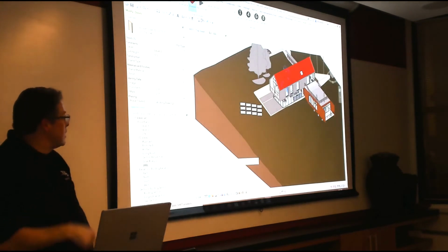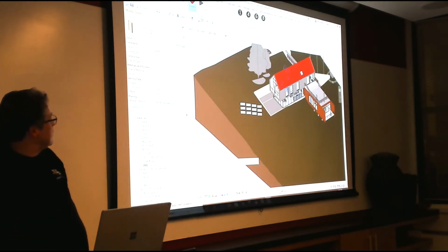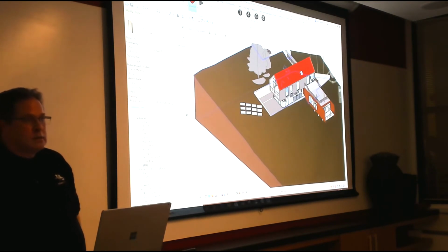You notice that Grasshopper ran, or maybe you didn't, but here you can see that the marks and the comments are now copied. So we read the mark parameter and put it on comments for all the doors in the project. All 10 in this case. But we can have some fun with this.